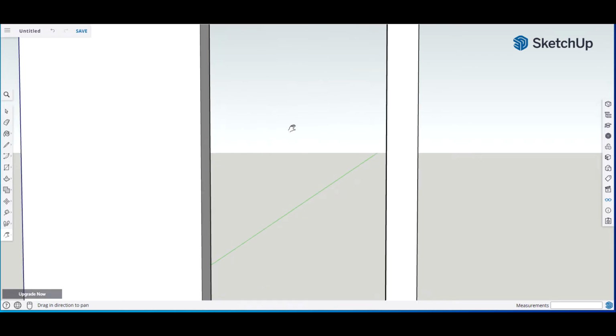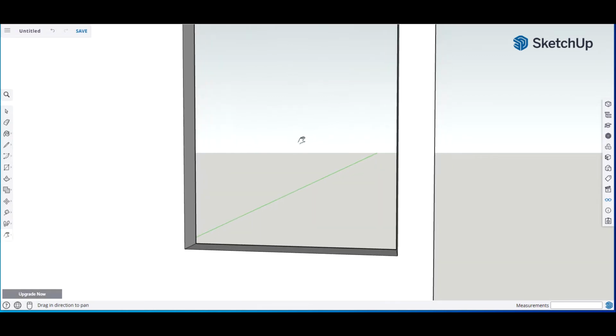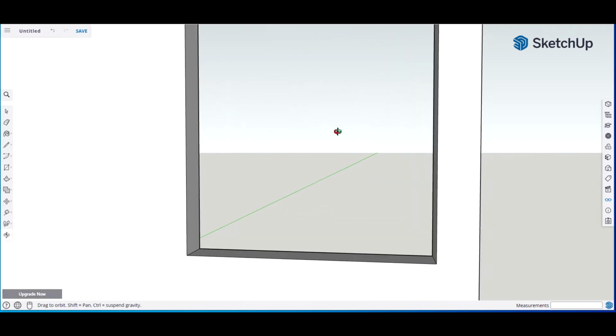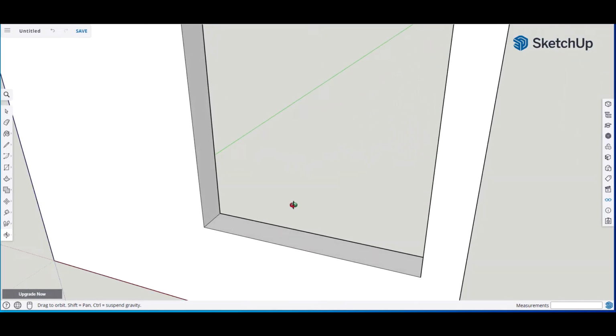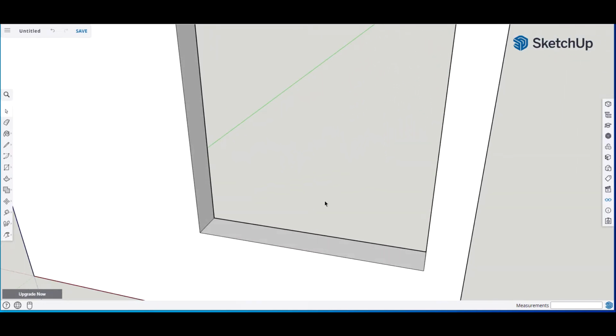So H, rotate here a little bit. So the strip that goes around is in the center of the wall here, and it's 1 1/4 inches wide by whatever the length of these dimensions are, but it's in the center, and so we would have to come in 1 5/8.